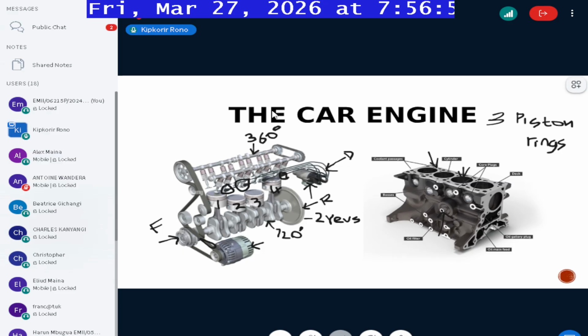The oil filter usually just collects any dirt and debris, any kind of mechanical particles from whatever is in the engine. So it protects very critical parts, for example, the crankshaft. The crankshaft is usually machined to very high tolerances. Sometimes, as the engine is functioning, you have some parts chipping off. Those parts can easily cause damage to certain sections of the engine that are machined to very high tolerances. So that's why the oil filter is normally meant to collect any dirt or debris that, for one reason or the other, could get itself mixing with the oil.